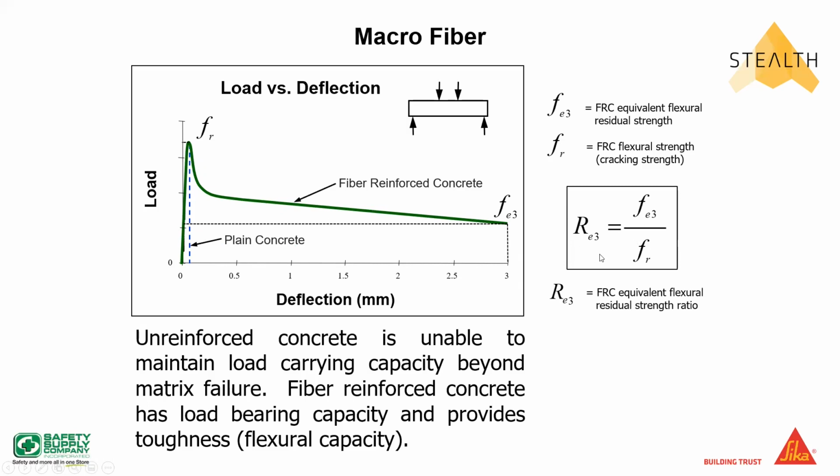Now, RE3, I don't know how familiar any of you are with this. If you've ever seen it in any specs, especially big warehouse slabs or big box slabs, a lot of times they'll have an RE3 value. Basically, it's the FE3 value, where the concrete ends after 3 millimeters of deflection versus where it cracked. It's just a fraction.